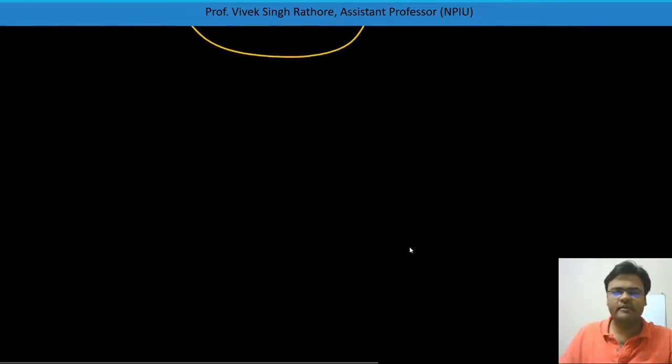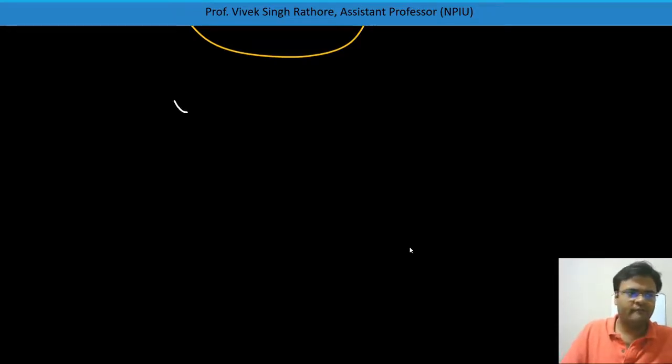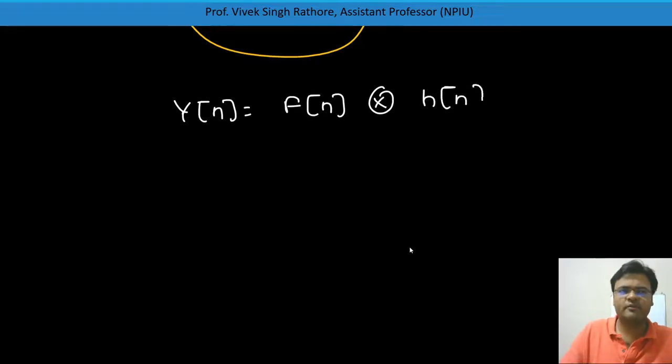Ultimately, in simple steps, whenever you are asked to convolve two signals, let's suppose f of n convolution with h of n, the first step is to change the domain. So you need f of k and h of k.